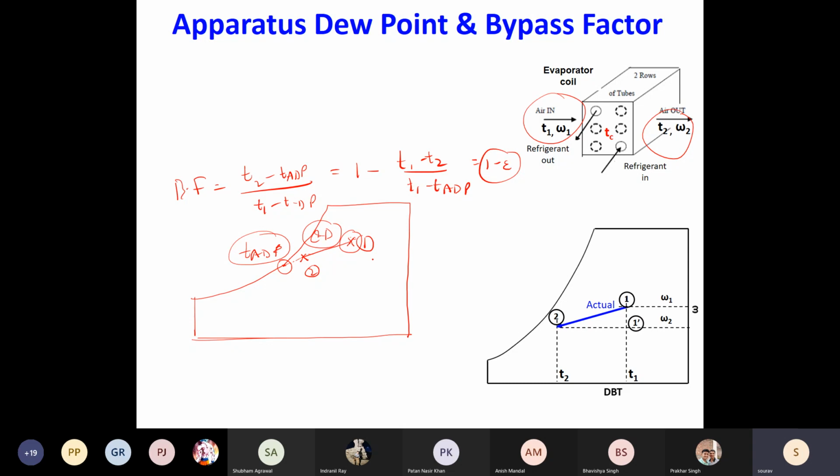It is not just cooling. So this is not the dew point temperature that we have discussed for the incoming air. In attaining the dew point temperature, we just sensibly cool. Here you are sensibly cooling as well as dehumidifying. So if you are doing both processes and you attain this temperature T_ADP, at that condition your air coming out from the coil would be saturated.